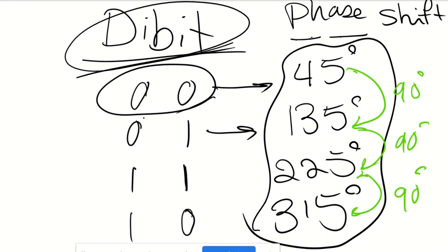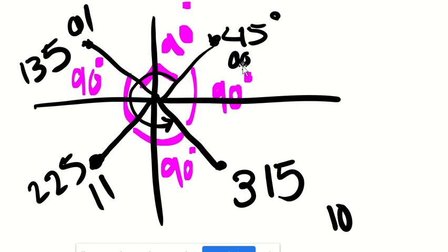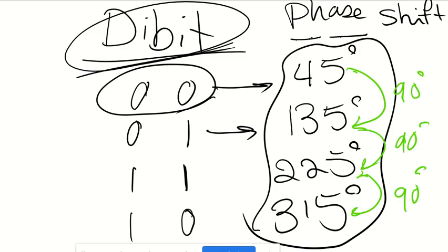I'm sure you have seen it in digital electronics, that instead of going from 0, 1, 2, you're changing 1 bit. If you remember from Karnaugh maps, we were just changing 1 bit and we were using gray code. It's the same thing here, basically. So I have 0, 0, 0, 1, 1, 1, 1, 0. In terms of electronics and modulation, this is a very smart way of sending information and increasing the bit rate, as you see. So it's pretty cool.